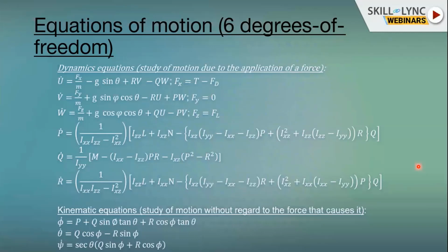When an aircraft is going through the air, the aircraft fuselage is not an aerodynamic surface. The wings are aerodynamic, but not the fuselage. So the fuselage is the body of the aircraft, and still offers a lot of drag. So you have to account for it; your thrust should overcome the drag force. That's why the resultant force in the X-axis is nothing but the difference between thrust and drag force.